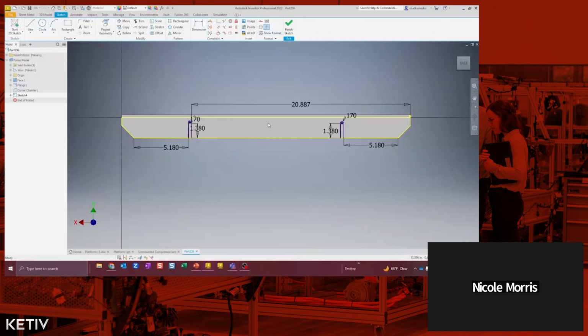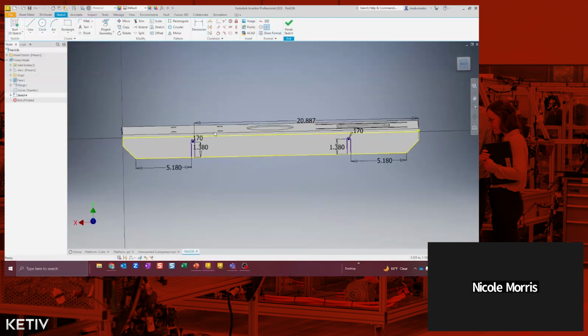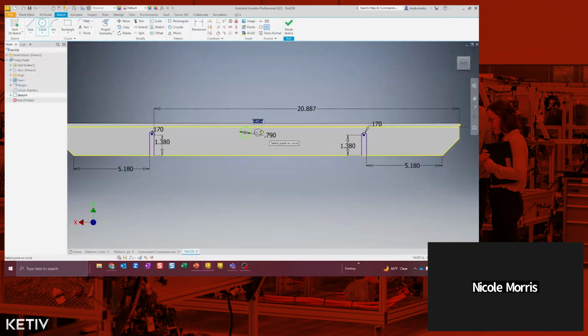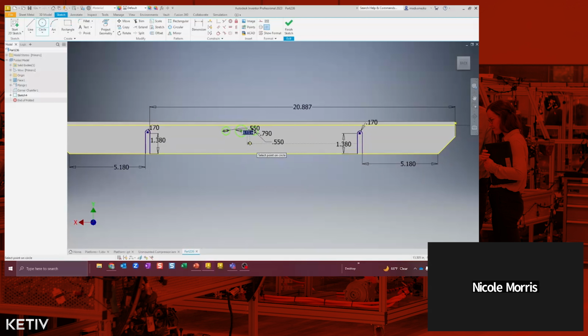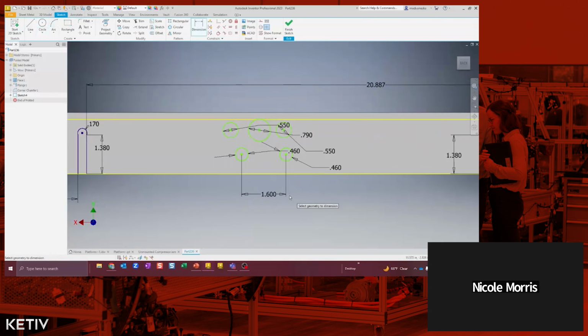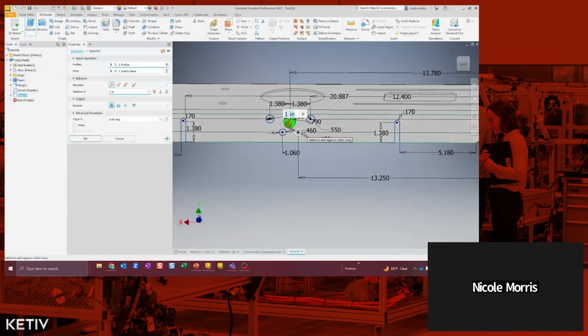Those will be the points where the mounting base actually mounts onto the bracket of the air pressure tank. So now that those are dimensioned out, I extrude out each of those holes.